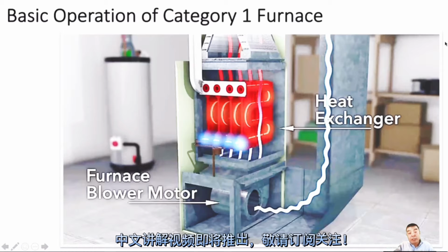Yes, so this is very important. Nobody repairs the heat exchanger. If it's a heat exchanger problem, normally we should change to a new furnace. Now for a new furnace, the heat exchanger has a lifetime warranty. So if the furnace is still new, maybe we can apply for a free heat exchanger and just change the heat exchanger.